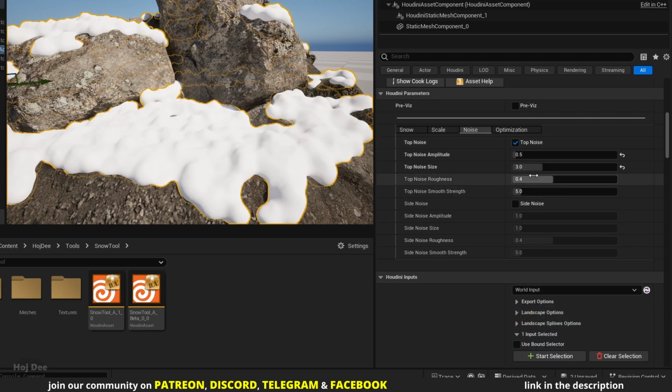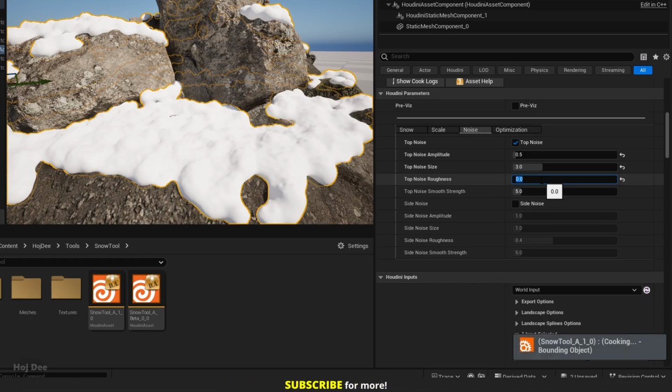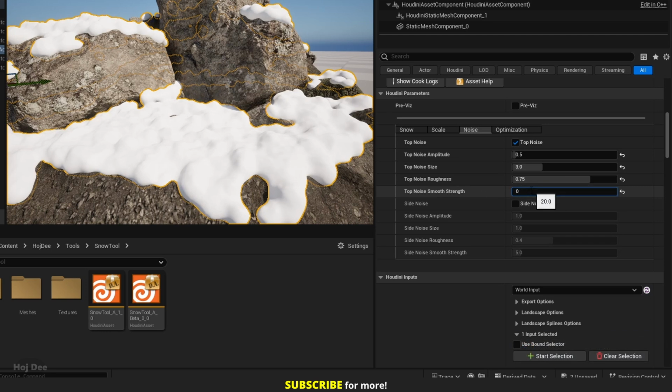If we increase the roughness to 1, it becomes rougher, and if we decrease it to 0, it becomes very smooth. A value of 0.75 is good. A smooth strength works the same but in reverse. Higher values make the mesh smoother and lower values make it rougher. So let's increase it to 20 and let's decrease it to 0 and it becomes really rough. The default value is fine.